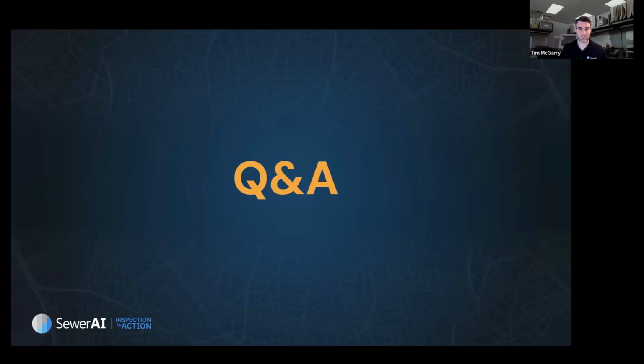Yes, we were looking at some data from someone who had submitted some data for a test. The pipe was indicated that manhole to manhole lining was recommended, but in one section of it, it had a deformed rigid 25% observation and also a protruding tap. So in the Smart Project Builder, without me having to really recommend anything or prompt it, it was saying, before you line it, you need to put a point repair here to fix the deformed rigid section, and you need to cut this tap back. The approach is included in the Smart Project Builder.